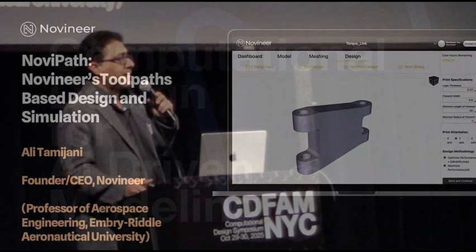So the way we took care of it is by using this two-resolution machine learning model. So what happened is, okay, now you assign the property, now you go from fine mesh to coarse mesh, you map the elastic modulus and other properties that you need. You map them to this coarse mesh, you perform finite element on the coarse mesh, you get the result, then you use your machine learning to map it back to the fine mesh, right?